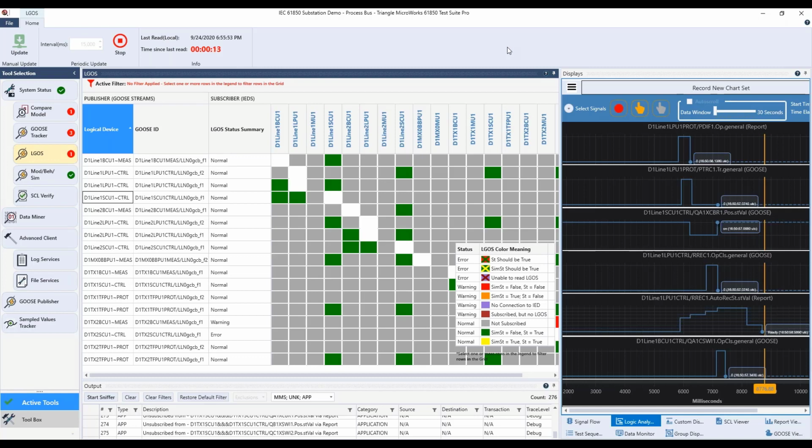From what you explained earlier, does that mean the IED should support the logical node LGOS? As I said, they are not mandated, but I would strongly recommend, and as an IED manufacturer, yes, I would strongly recommend you to support that, because it helps your customers. It also helps you when you have to do some testing of your devices.